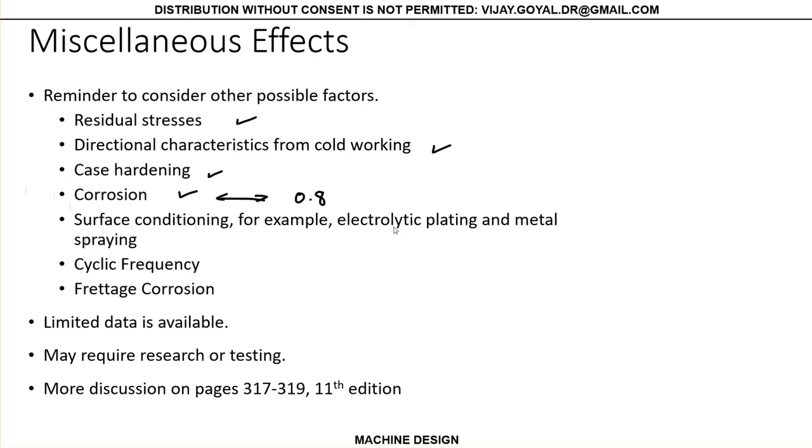Sometimes we spray your panels so they don't get corroded, but that actually affects fatigue; you pay a penalty for it. If you have any other factor, maybe going high speed, then maybe you include a speeding criteria there, et cetera.